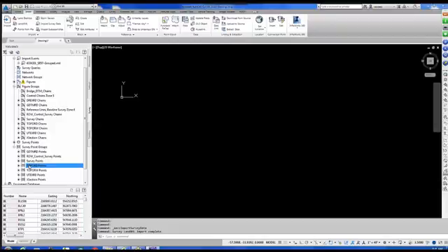Now, I've got the data. We've gone through the whole process, taking the raw LandXML file that came out of CAiCE, we viewed it in the LandXML viewer. We then brought it into the LandXML grouper. We then applied those filters to build those groups. We then created that grouped LandXML file. We came into Civil 3D. We told it where to store the data, what folder. We told it the format of created a new survey database, and we told it the format of that database, what coordinate system is working in, and we told it to also bring in the extended entity data.